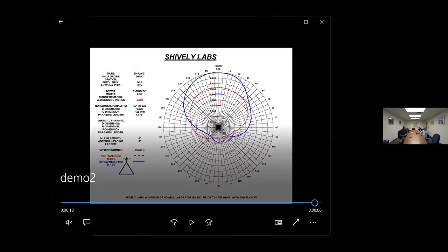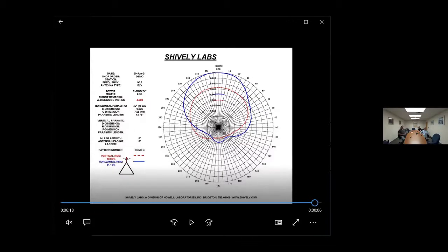Okay, here's what happened. So you can tell that half power beam width got sandwiched up really tight. There's sort of a disparity between the H and the V now. So if this certain pattern came close to fitting in whatever DA I had, I'd probably work with the H and the V ratios. Do that by pulling or pushing the bay further away from the tower or closer. We're already 4.5 inches out, so I might mess with the parasitics there a little more.